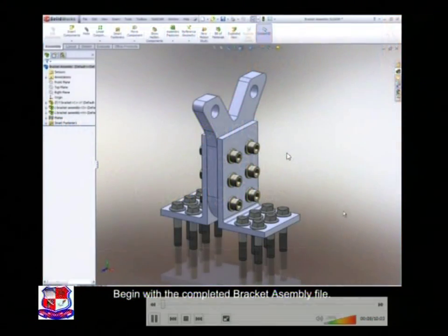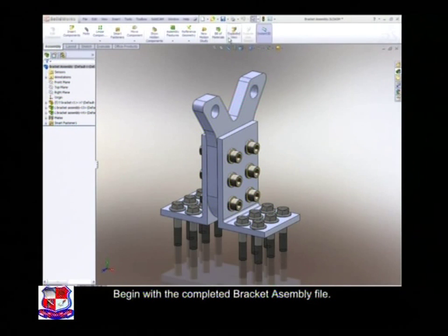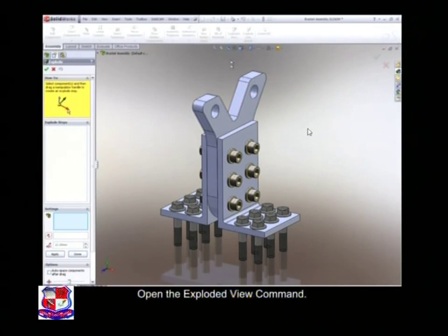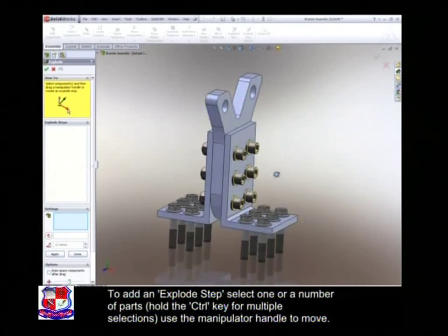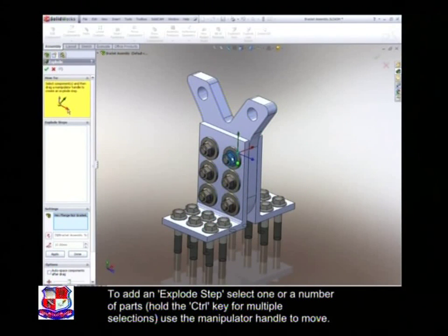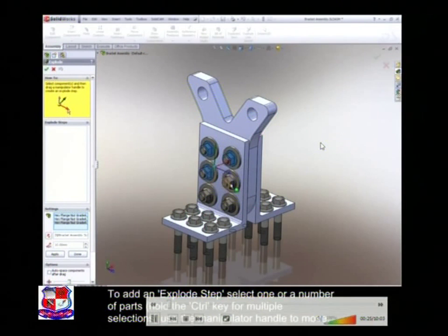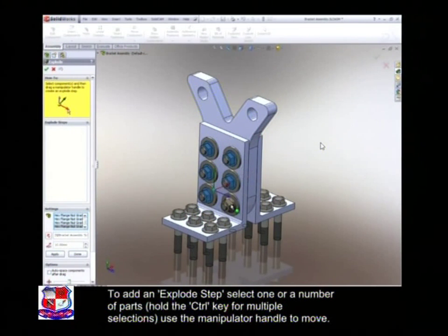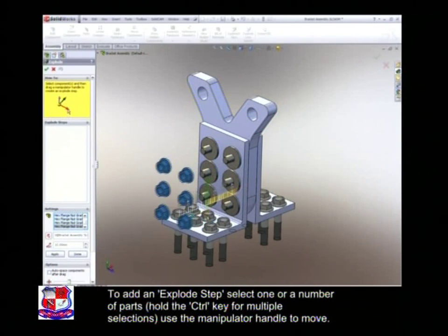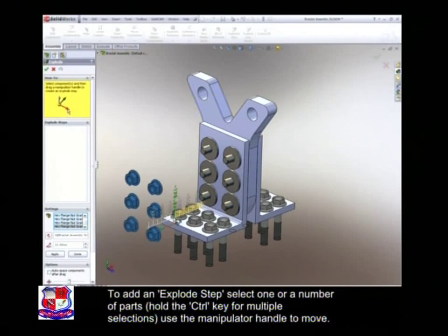This is one typical assembly drawing, an assembly of the components. If we draw this assembly as is, it would be difficult to understand how it is working. Here 6 nuts and bolts are there as shown over here. So we disassemble all these nuts to show them like this, moved at a certain distance.